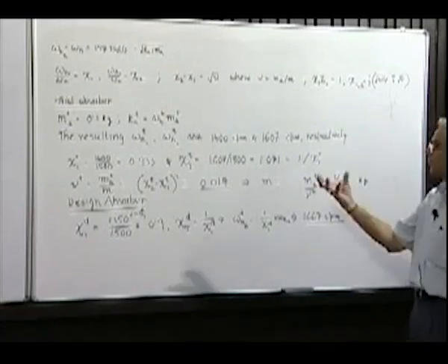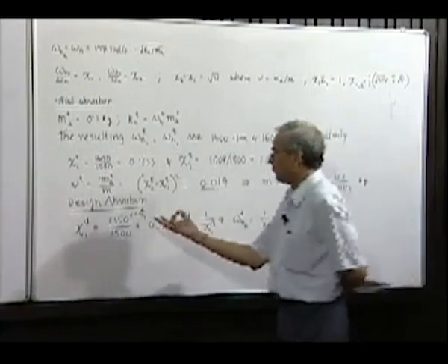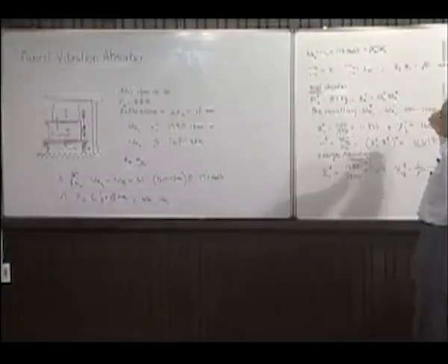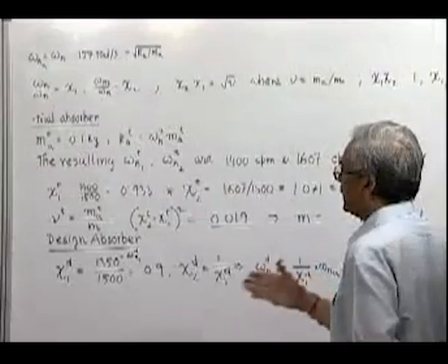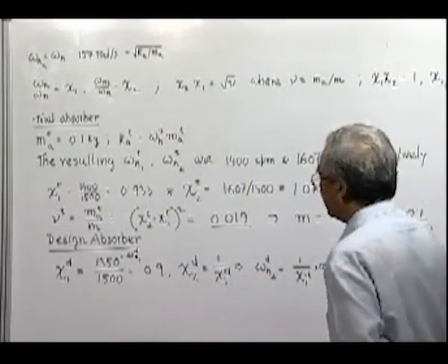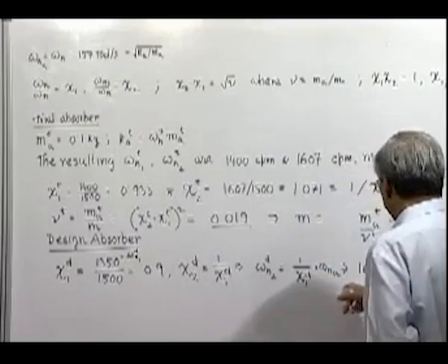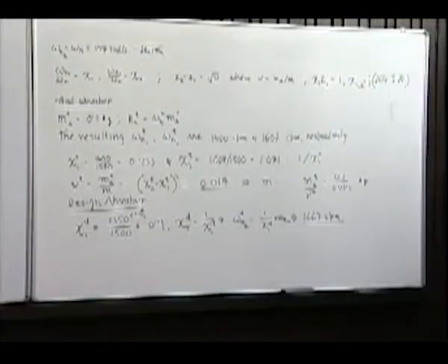We have also put a design absorber in such a way that the lower natural frequency is exactly equal to the limiting value, to avoid any large oscillation when the exciting frequency varies, and then the upper frequency is above the other range. That means we are satisfying that condition. So, the other condition, that is the rattle space, now we have to see.